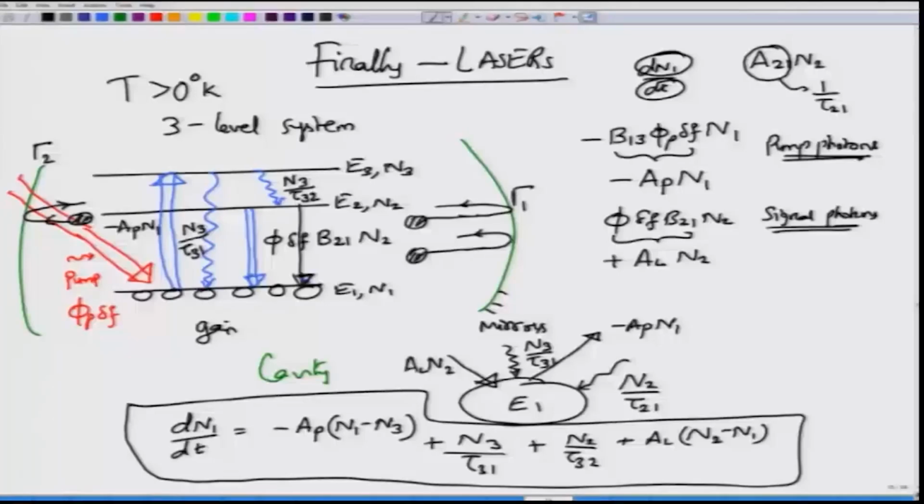Okay. But because you want to take this out also, you do not want all the radiation or all the power to be inside the cavity. You want some of that power to actually come out of the cavity. What you do is you take gamma 1 to be around say 99%. So, 1% of the radiation is actually tapped out, and you take gamma 2 to be 1, which means there is 100% reflection on one facet and about 99% reflection on the other facet. There is nothing sacred about 99%, you can take whatever percentage.